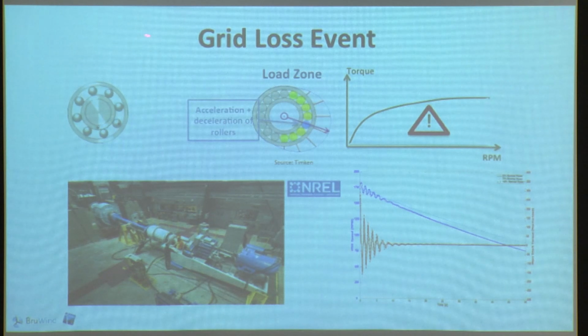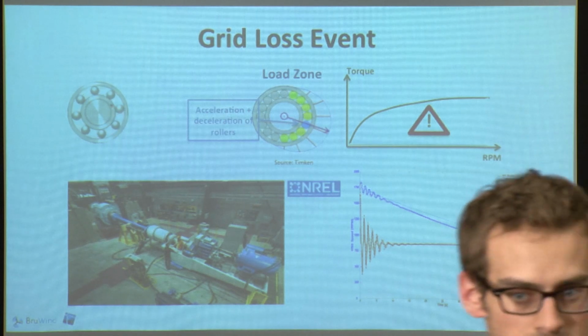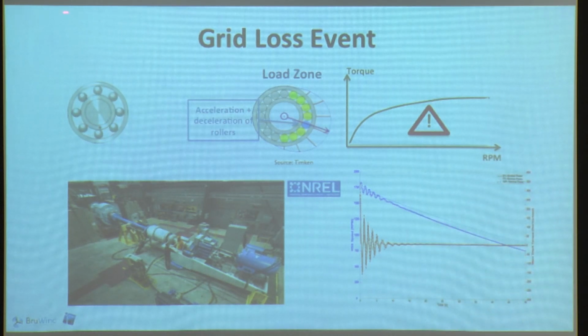Basically what a bearing does is you have a shaft in the middle and then rollers in the case. This is with balls, but in the case of turbines you have rollers that allow the shaft to rotate in a fixed frame of reference. So the housing is fixed, the outside ring is fixed, and the shaft can rotate. The rolls will facilitate this, so they will roll along, and they will do this without sliding.